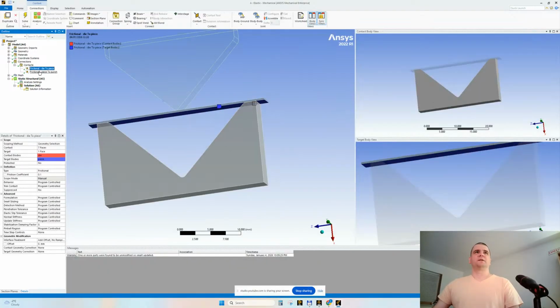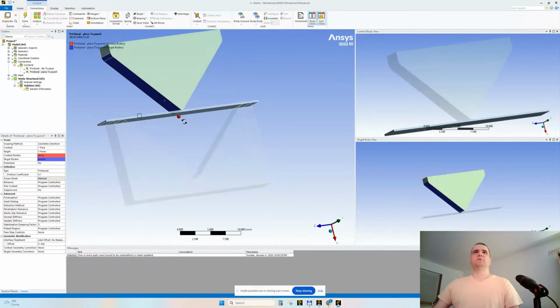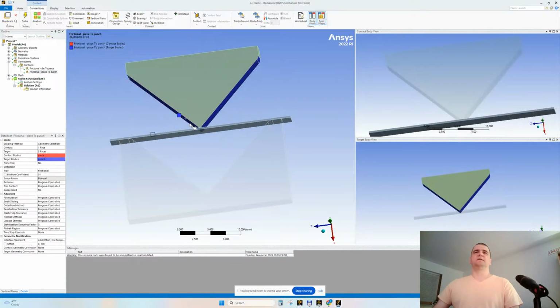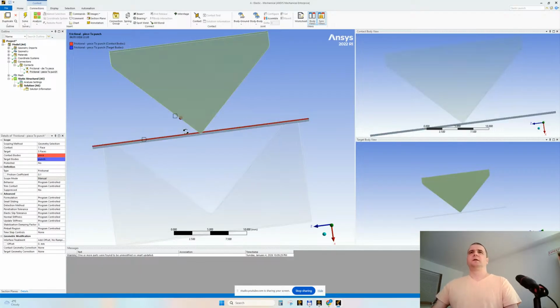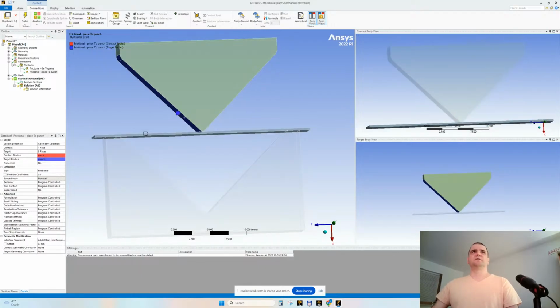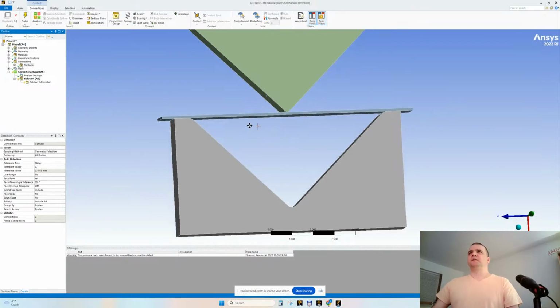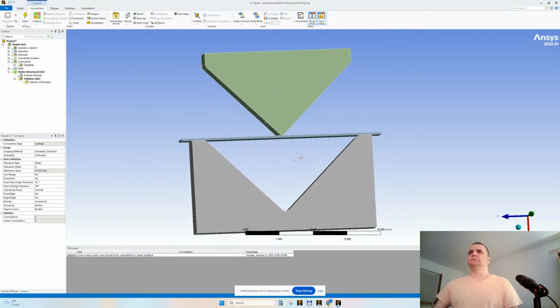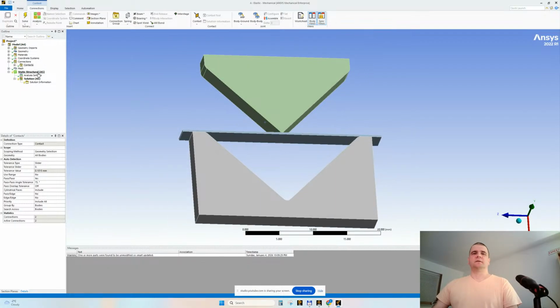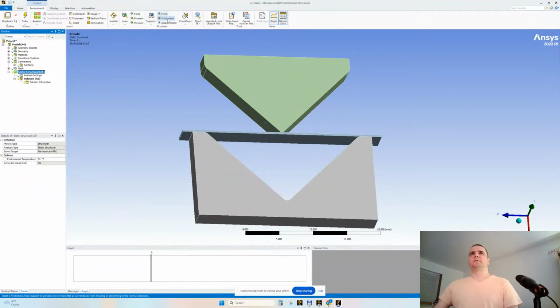I'm looking for additional contacts that it may have put, but no, because it didn't modify geometry, only made some measurements, so there is no additional contact. All right, let's make it very, very simple regarding the boundary conditions. Very simple would mean something like this. This is a fixed face.